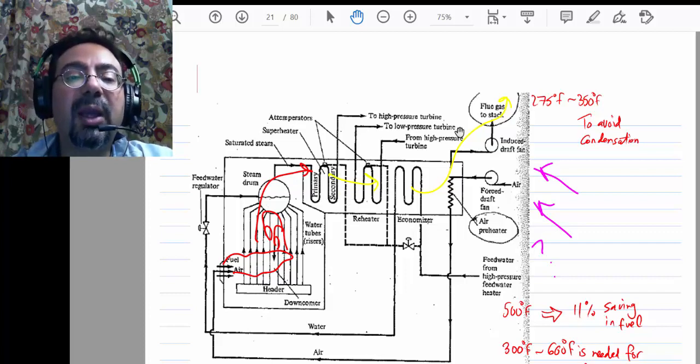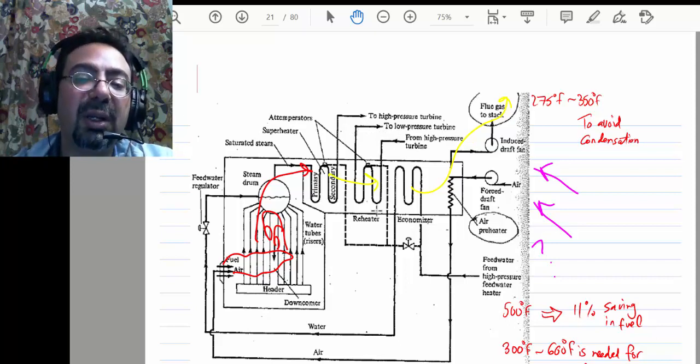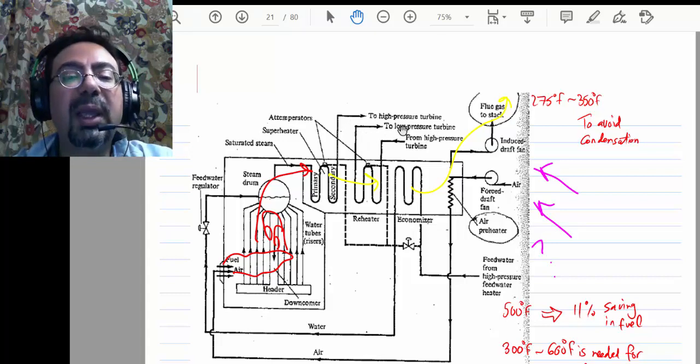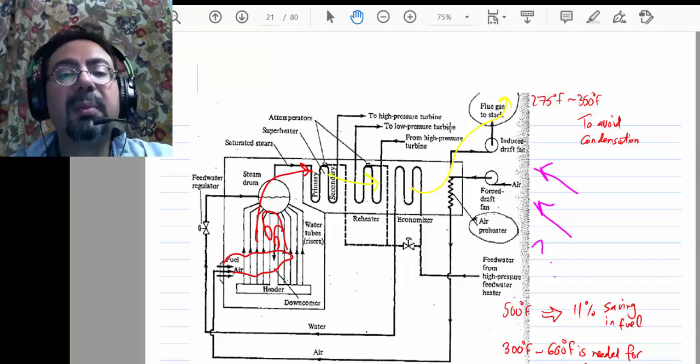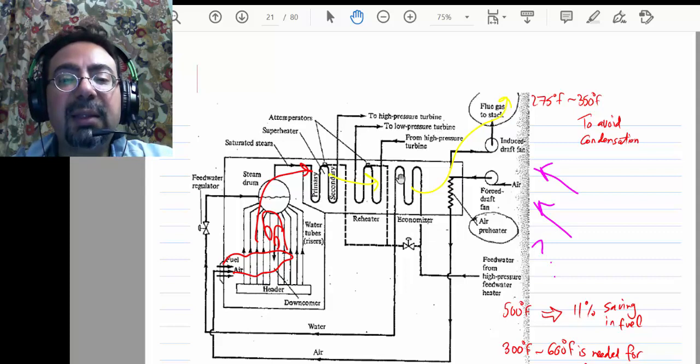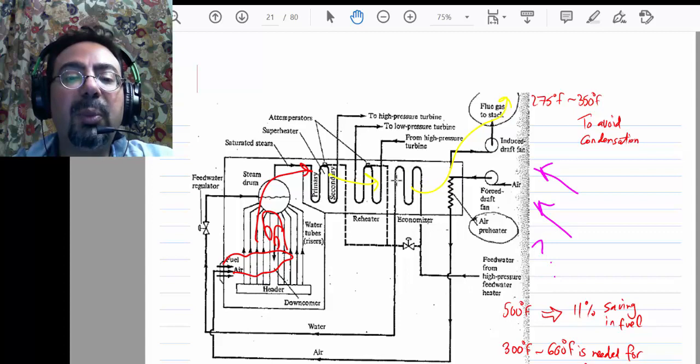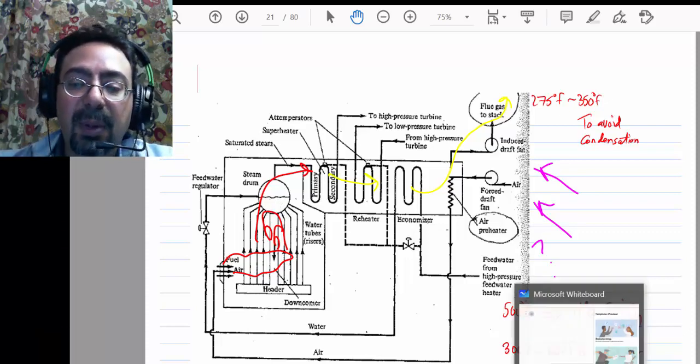That is the steam coming from the high pressure turbine exhaust and going back to the intermediate turbine. And then after that, that's the economizer. What's the economizer? It's the first place that the water goes into the boiler. It takes the water up to saturation, and then it goes into the drum, and that's when it continues on its path.